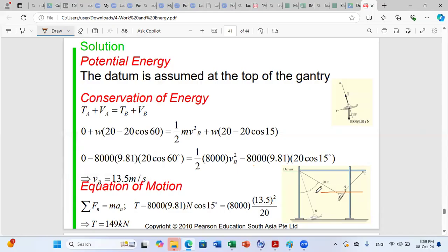and you want to get, as you said, V gravitational at A will be 0 because you considered the datum at A. Now at B you are below the datum, and you have a negative gravitational potential. You should consider the distance below the datum. You need to say that VB is minus M times G times this distance d. Now, how can you calculate d?